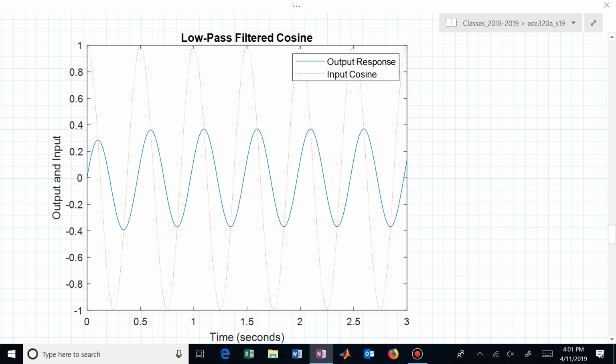What's tau? It's due to the low-pass filter, isn't it? That's 1/5. So we should be expecting the transient to be gone, the beginning to be gone after 5 tau. Tau is 1/5. So after a second, we've kind of hit our groove. Now we're just doing a sinusoidal steady state. And does the blue look pretty much the same period as the red? Are they aligned? Are the peaks aligned? No. There's a delay, which is our phase shift.